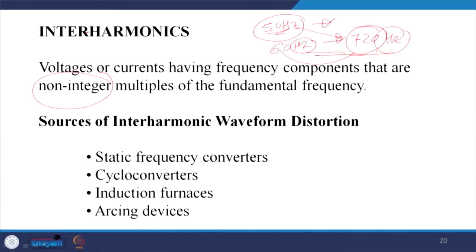More of it will be eliminated by the low pass element, but due to the interharmonics, sometimes low frequency comes into the picture, the subharmonics. Then you have a lot of problems eliminating them. So we generally do not use interharmonics while choosing the PWM and so on. If they arise, it is a very nasty element, and eliminating this entity is quite difficult.